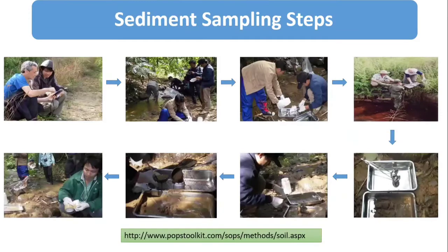Now again, we are in the sediment sampling location. As I said before, first we have to note our latitude and longitude using our GPS system. Then always wear new clean latex gloves while sampling. Then thoroughly clean all sampling equipment with metal-free soap and deionized water prior to sampling at each site.